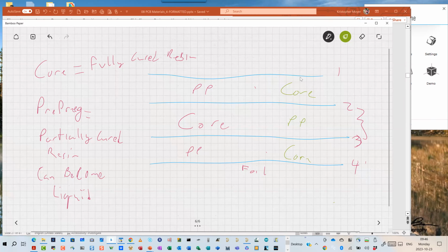And I would have to process the first core and the second core separately to etch their two inner layers. Then I'd have to glue. Then I would have to laminate the whole thing together. Then I'd have to drill and etch the outer layers. So while it can be done, it's not as good of an idea to do it this way.